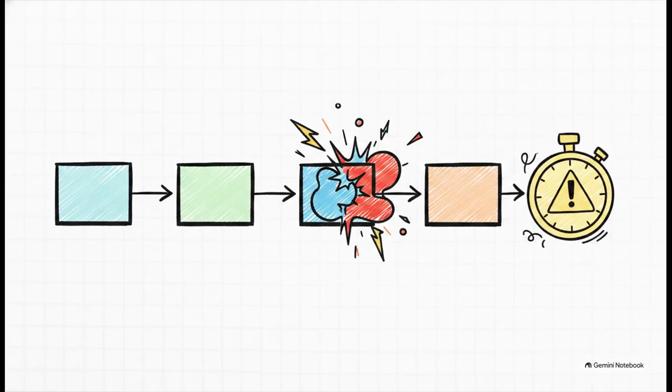Now here is the absolutely crucial point for scan shift mode. Hold timing is everything. From an STA perspective, when we're analyzing the timing of that scan chain, we have to make sure data does not reach the next flip-flop in the sequence too early. It's kind of like a group of people standing in a line, waiting for a camera flash before stepping forward to the next mark. If someone moves way too fast, they literally bump into the person ahead of them. The data collides, and the sequence gets overwritten before it's properly set up. STA verifies this hold timing to prevent that exact crash.